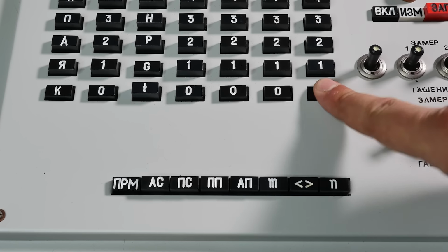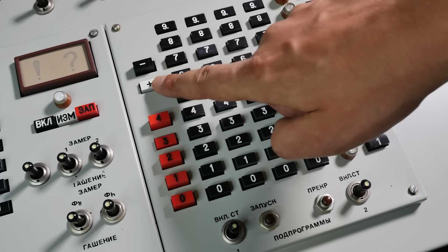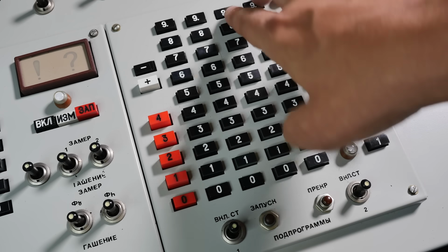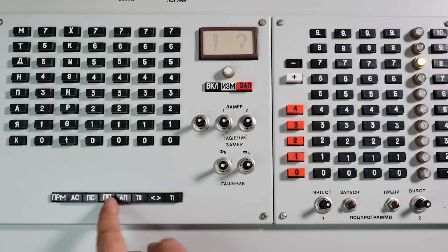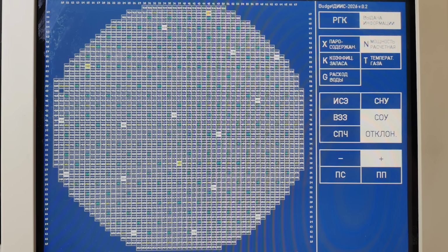So, in this case, on the left keyboard you enter the code and select one of four set points. And on this keyboard you select plus for greater or minus for lower. And then you always type 3 zeros, and the last two digits are that percentage. So say I want to see all channels where power exceeds their warning high set point, which is 2.93 MW, by 2%. And this is what we get.